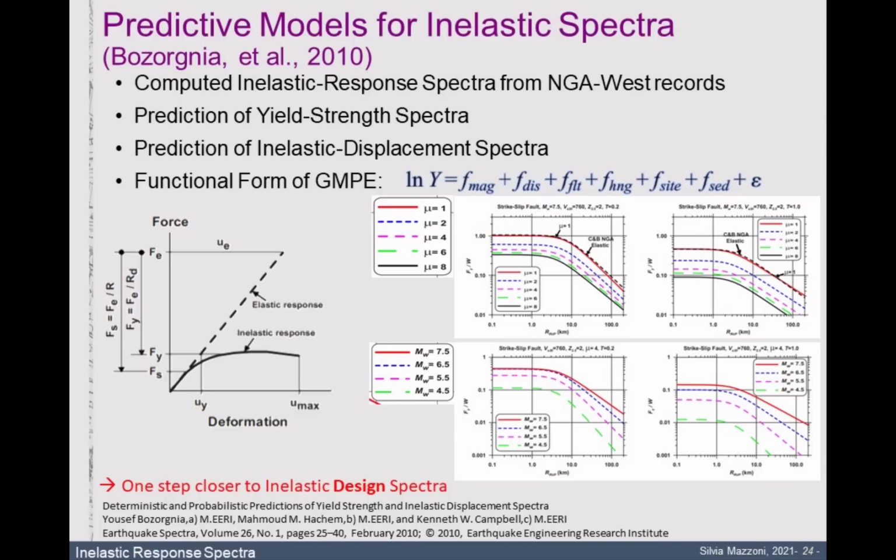Here's your constant ductility spectra, where now on the vertical axis is F_y as a function of W over W here. So always read what's on the y-axis, okay? Because it's often different, and make sure that you have the definitions there. And in this case, they actually did use 5% damping, for example, in the database because they were running the whole range. And so you don't want to have discontinuities when you go from R factor of 1 to 1.5 to 2.